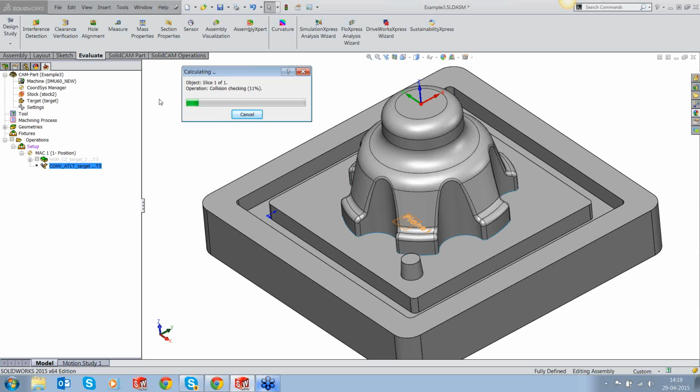What I can say is whoever is in the mold making industry and has a 5-axis machine can extensively use this feature. They could take a 3-axis toolpath, an HSM toolpath, and immediately convert it to 5-axis and run it on their 5-axis machine. So you are allowed to use smaller tools, smaller diameter as well as smaller length, which allows you to go deeper into the part without having to compromise on the L/D ratio issue.